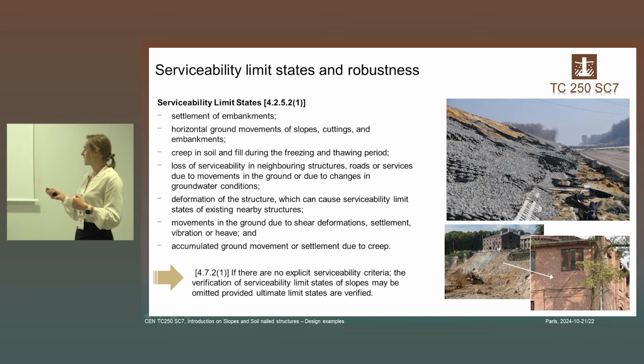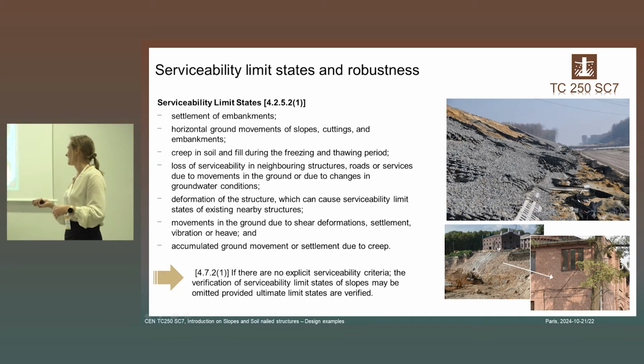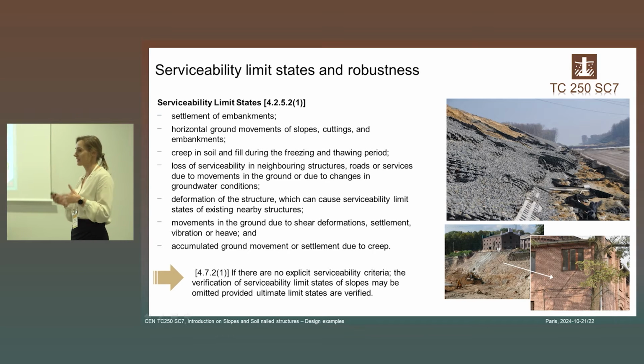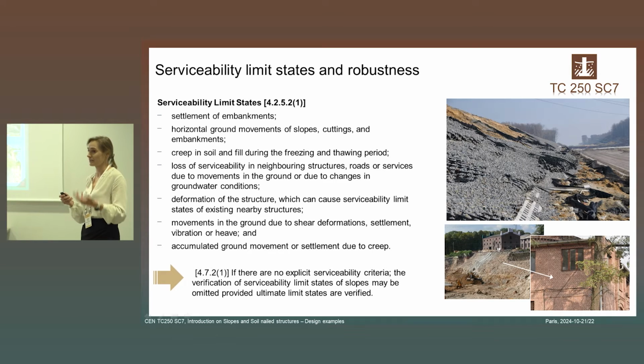Regarding serviceability limit states, there is another list of considerations, but I think one aspect is really worth noting. If there is no specific explicit serviceability criteria, the verification of serviceability limit states of slopes may be omitted, provided that ULS is verified. I think it's quite convenient, especially for the designs based on limit equilibrium methods.